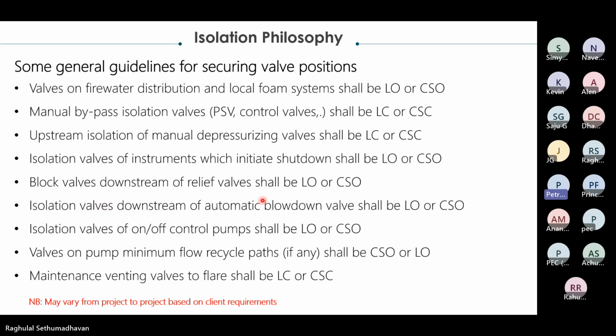Block valve downstream of relief valves, as we saw, lock open. Isolation valve downstream of automatic blowdown, also lock open. Isolation valves from on-off controlled pumps, that is important, that also lock open. So pump recycle line, lock open. Maintenance main valves to flare, lock close.